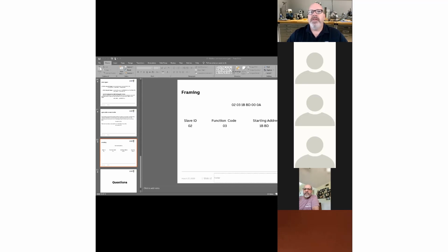An offset would be if somebody said, oh, you need to read the 40,000s, but what they really mean is read 47,101, but put in an offset of 40,000. So we can actually read the registers that you're looking for, but we're not going to do an offset here. There's going to be a 0 offset because I specifically want to read register 7,101.